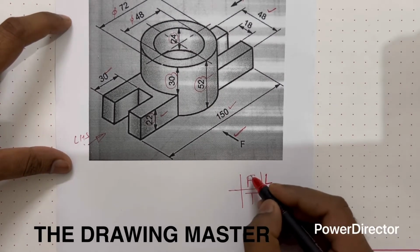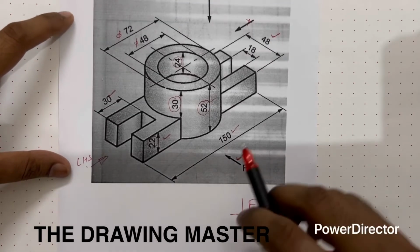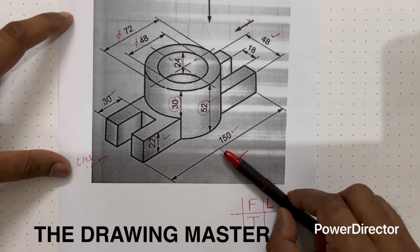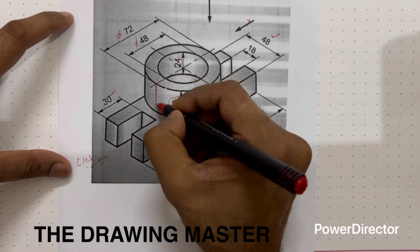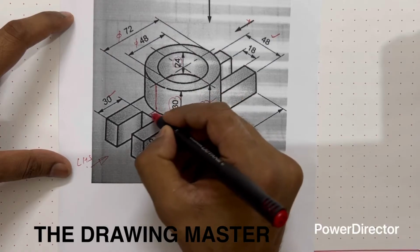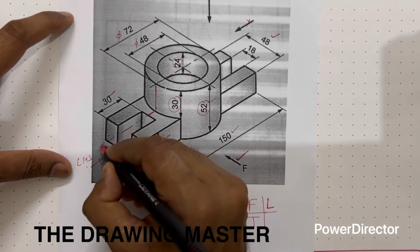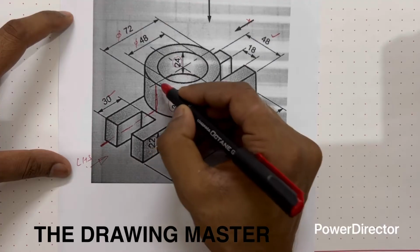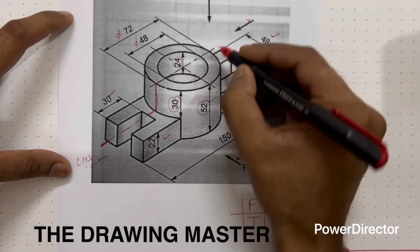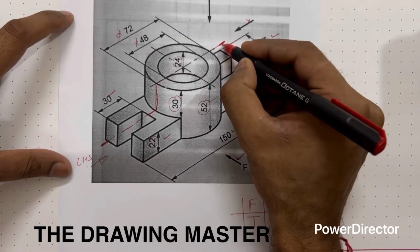So we'll draw front view and left side view as a sectional view. If this is the front view, for sectional front view, the cutting plane will be here. The object has to be sectioned from this plane for sectional front.